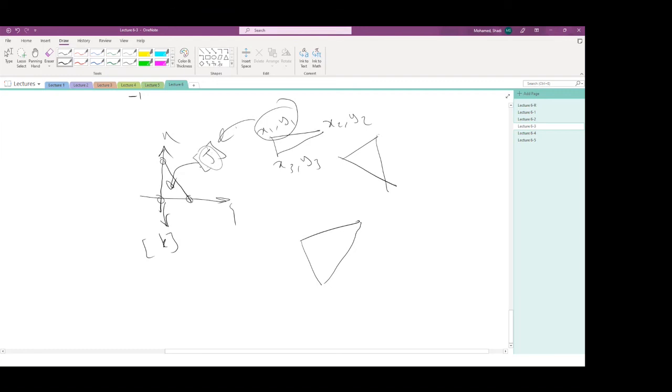So you need to find the Jacobian, insert it into this expression we have derived for this reference element. It gives you the stiffness matrix for this element here. And you repeat the same thing for all these elements. So you have the coordinates, x and y. You insert them into the Jacobian. You get the stiffness matrix for this new element, and so on for all of them.